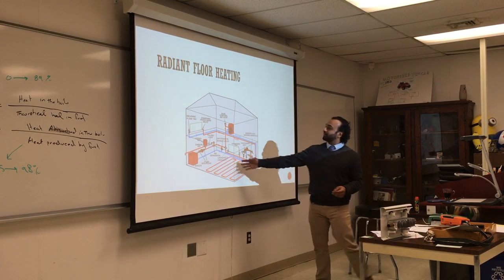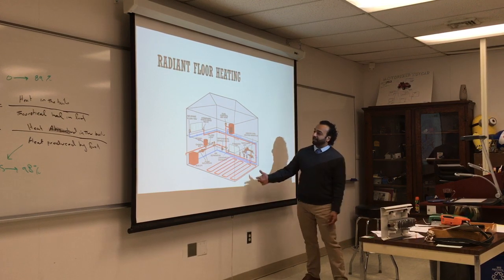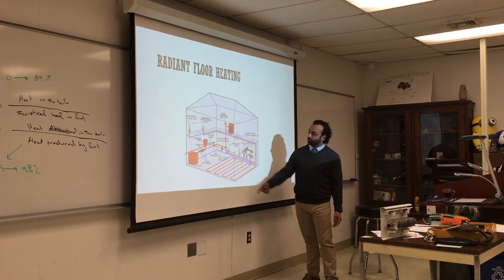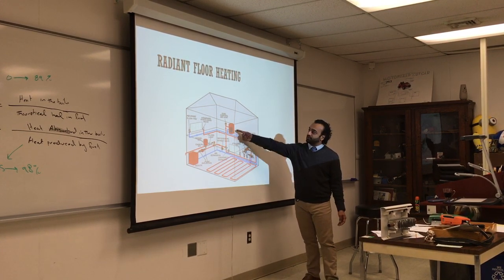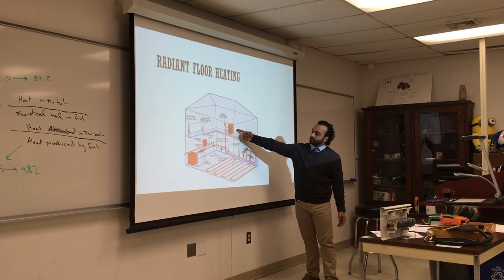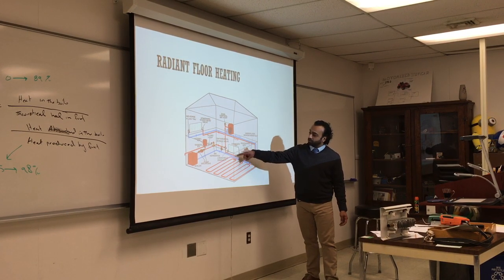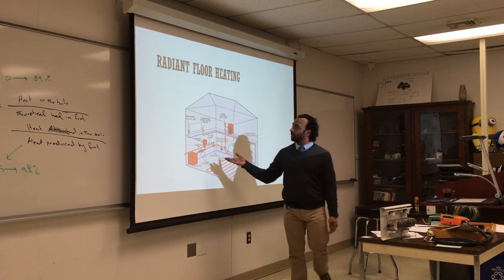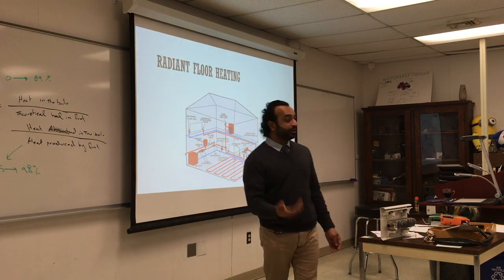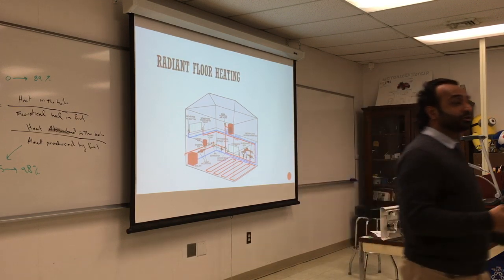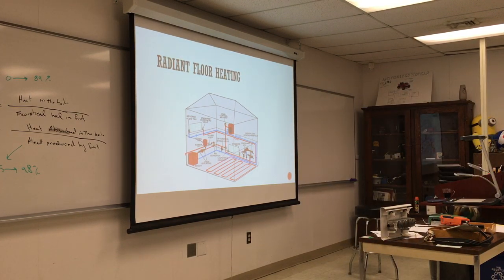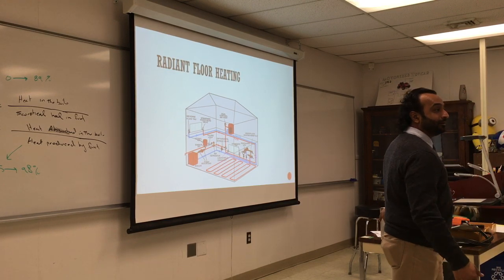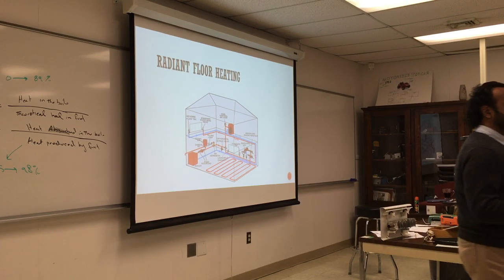Yeah. So again, this is a combination of all the stuff we can use with hot water. We can do radiant, an auxiliary heating unit, and this is another unit you can run water through. That's in the wall. So what I'm trying to show here is that there are options in radiation. You can have hot water. You can use some of that hot water for radiant, some of that water for baseboard. And I want you to think about that in your project.